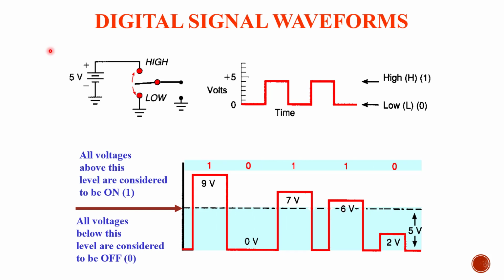Now, when we talked about oscilloscopes, I mentioned that it's not always good enough to measure a voltage with a meter, because typically a meter measures averages. And if I'm looking at this data stream, I may get an average that's not even representative. That's not going to do me any good.